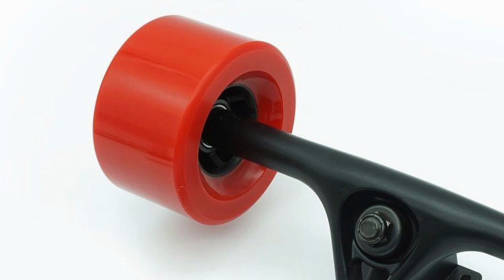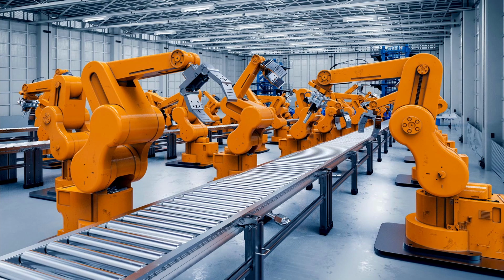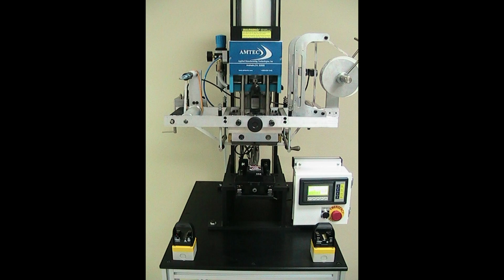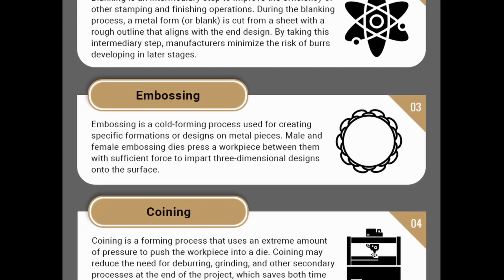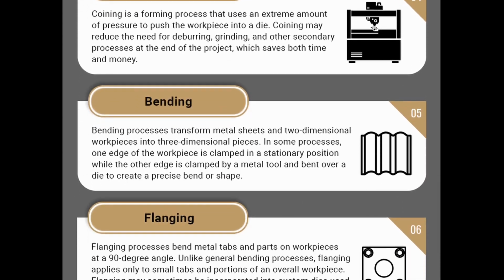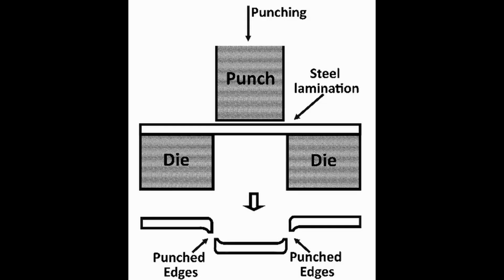that happens when skateboarding. The most suitable manufacturing process is the stamping process. The primary method of the production of washers is stamping. It is used to convert flat metal sheets into specific shapes, and it is a complex process that can include a number of metal forming techniques such as blanking, punching, bending, and piercing. In the making of washers, we will use the punching technique.